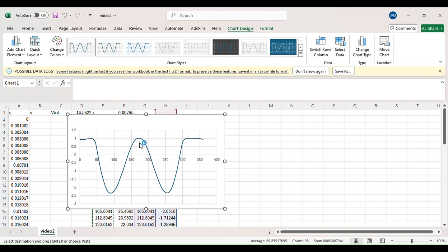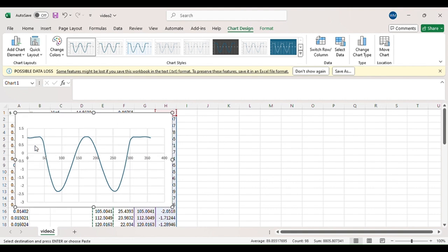And another minimum, or another maximum, I should say, occurs at approximately the 180 degree mark, which corresponds to a stagnation point where coefficient of pressure would be maximum. And then same occurs at 270 degrees. And looks like it maximizes at about 310 degrees when in fact it should maximize at 360. So there are some errors which are likely caused by numerical errors, meshing refinement errors, possibly rounding errors. So there's plenty of things to explain, but generally it looks acceptable because it has that general squared sinusoid.